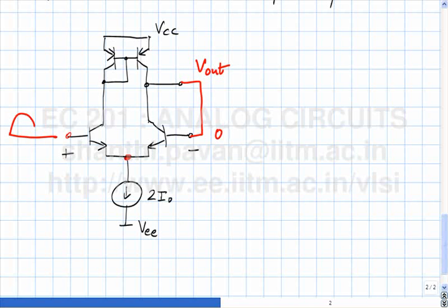If I put a sine wave of amplitude A, what will be the output? The incremental gain is virtually 1. So this will also be a signal of amplitude A. Alright? If this is A, how high can this voltage go?